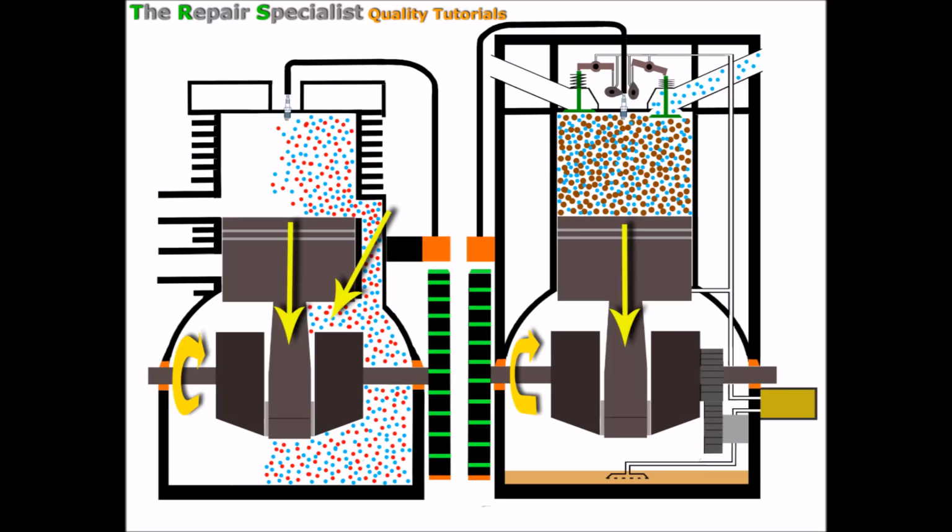So as the two-stroke piston lowered, it created a pressure beneath it, and in doing so it compressed all of that air and fuel mixture. And because it was compressed, there was a pressure there that needed to be released in order for the piston to come down to its lowermost point. But the pressure couldn't go back through the inlet port here because the piston is blocking its route. So the only way for that pressure to go now, the piston's in this position, is this way through the transfer port, which is open now specifically because the piston is sitting in this position.